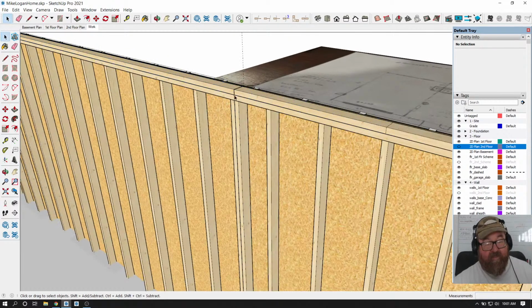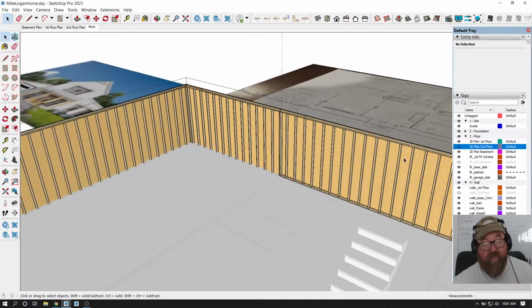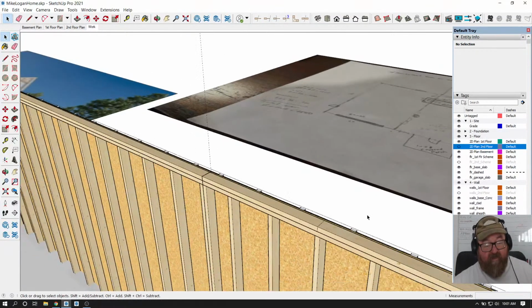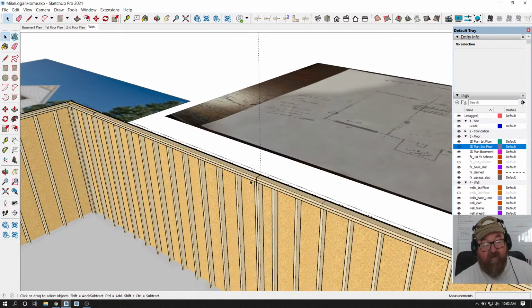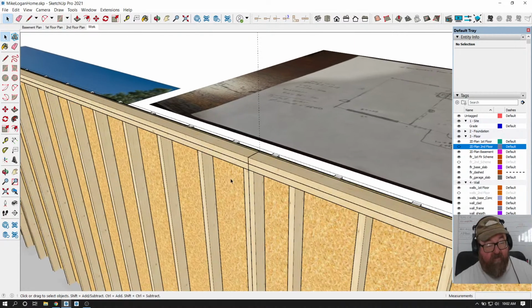So that is the purpose of the top plate, is to tie all of your individual walls together if you had to build them in sections. In other words, we would never build that in one big long wall anyway. It'd take 10 guys to raise it up. But we build them in sections, probably 2 sections, or in this case, these would just be built as 2 different walls. We would leave off the top plate on a section, and then come back after the walls were stood up and nail that plate on so that it spanned that joint right there.